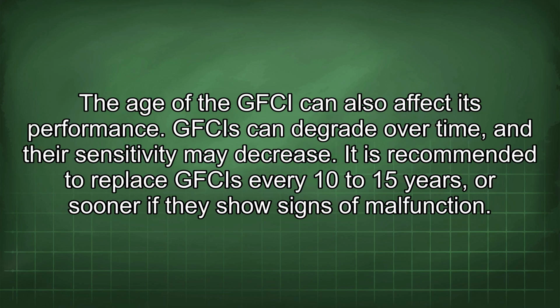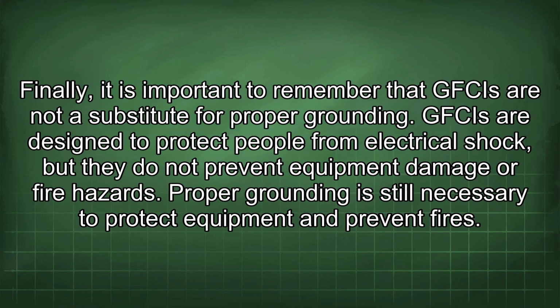The age of the GFCI can also affect its performance. GFCIs can degrade over time and their sensitivity may decrease. It is recommended to replace GFCIs every 10 to 15 years or sooner if they show signs of malfunction. Finally, it is important to remember that GFCIs are not a substitute for proper grounding. GFCIs are designed to protect people from electrical shock, but they do not prevent equipment damage or fire hazards. Proper grounding is still necessary to protect equipment and prevent fires.